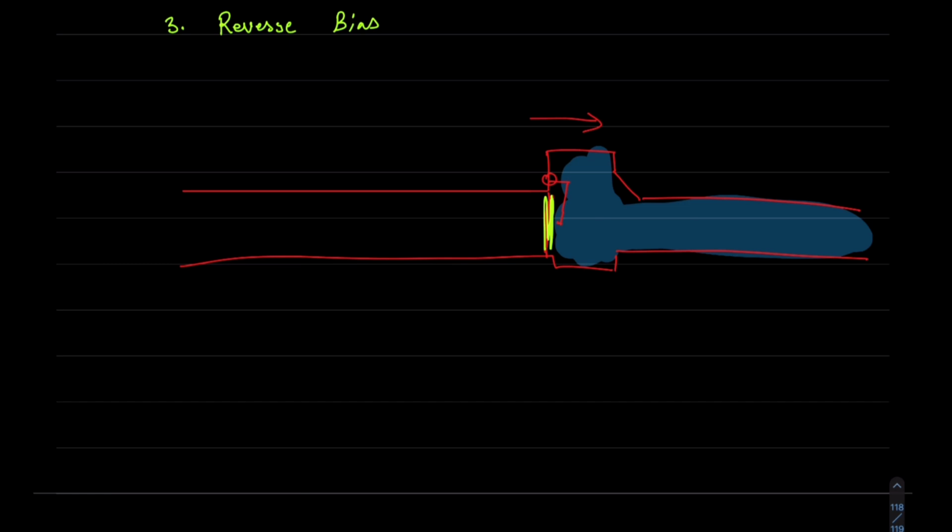So remember this water pipe thing is a very good analogy for the PN junction diode under different biasing. Under forward biasing, the water is flowing from left to right, so it allows the current, right? Under reverse bias, the PN junction diode stops the current, except the saturation current, which is extremely minute, right?